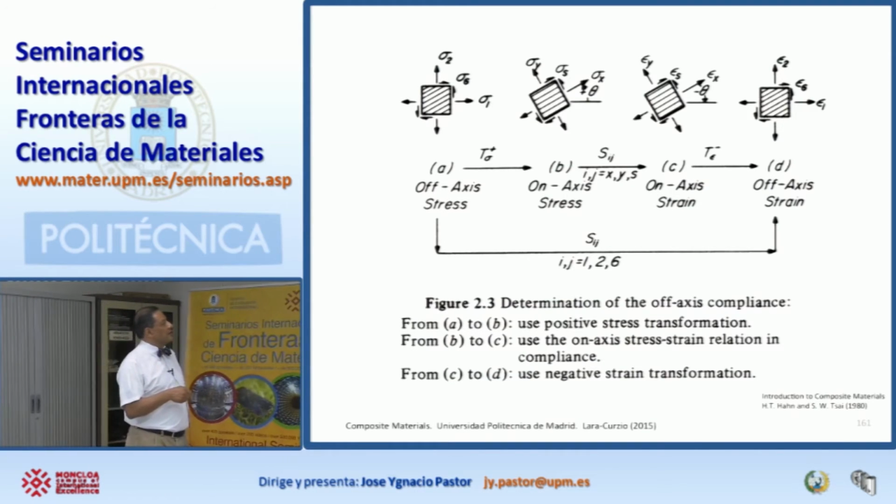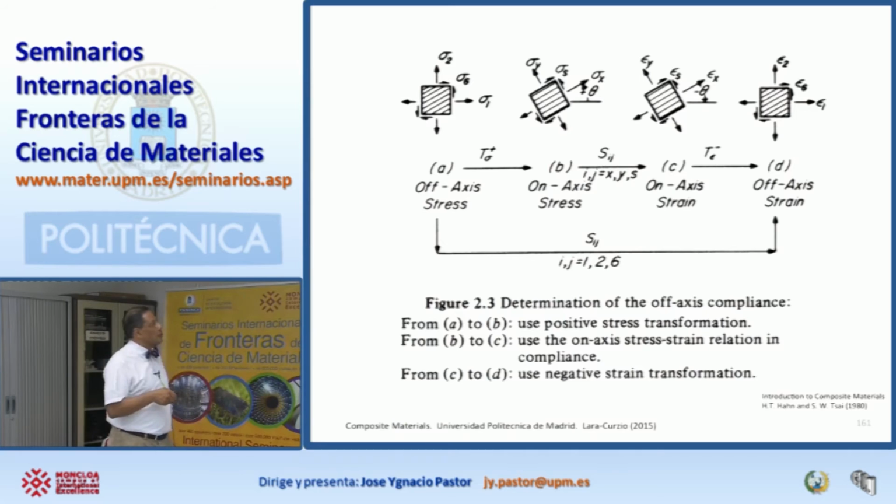The first thing that you have to do is you do a transformation for your stresses, where now you look at your stresses in the x or y direction, which is the direction of the fibers or perpendicular to the fibers. You have your elasticity relationships for the fibers. So once you have your axes aligned in the right direction, it's very easy to go from stresses to strains. I just showed you those matrices. And once you have your strains in the direction of the fibers or perpendicular, then you do another rotation, and you go into directions 1 or 2. And that's it. These are just linear transformations. And the only thing that you have to pay attention to is whether you have a positive transformation. In this case, you see how it says plus theta, because we have rotated this angle in this direction to get to x.